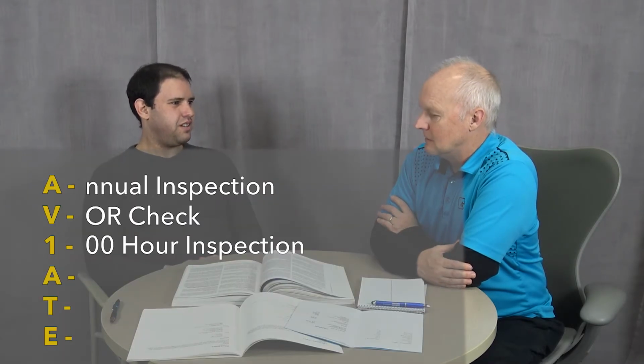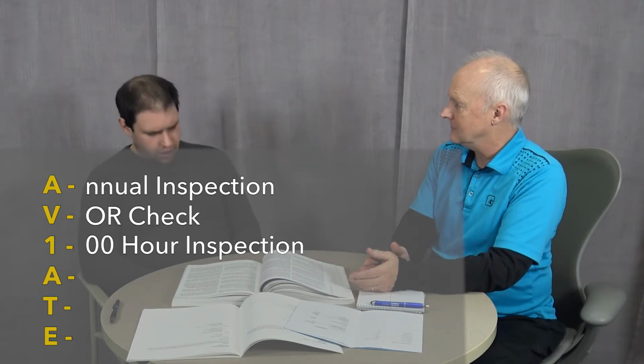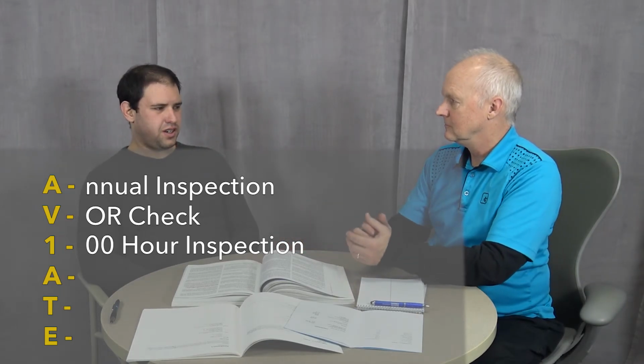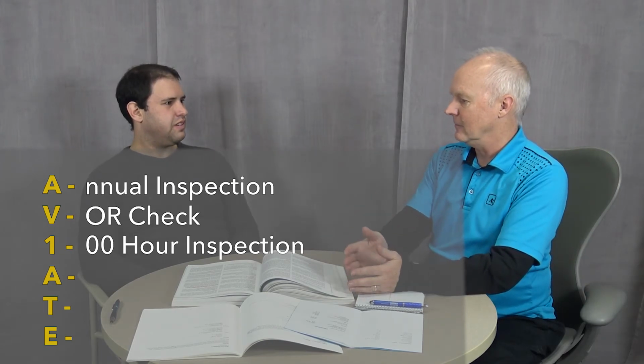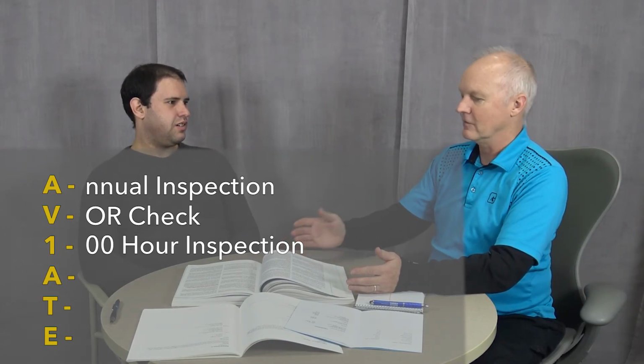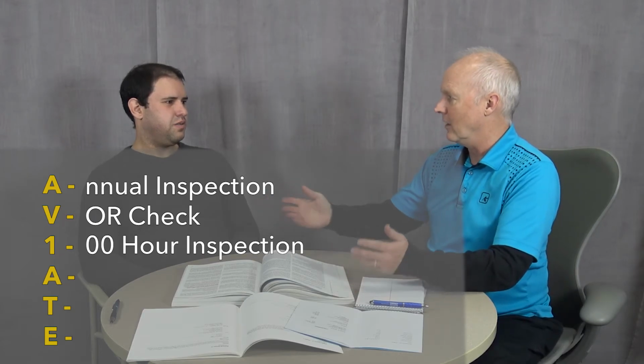It could, if we run the hours up. But the airplane would have to fly more than 100 hours in a year, which I don't think is pretty regular flying, is it? Right. So if we don't hit the 100 hours, the annual zeroes it back out? Correct. The annual can count as a 100-hour inspection. So if we get our annual today, then we don't hit 100 hours until next year. When we have our annual, then we're on a new 100.